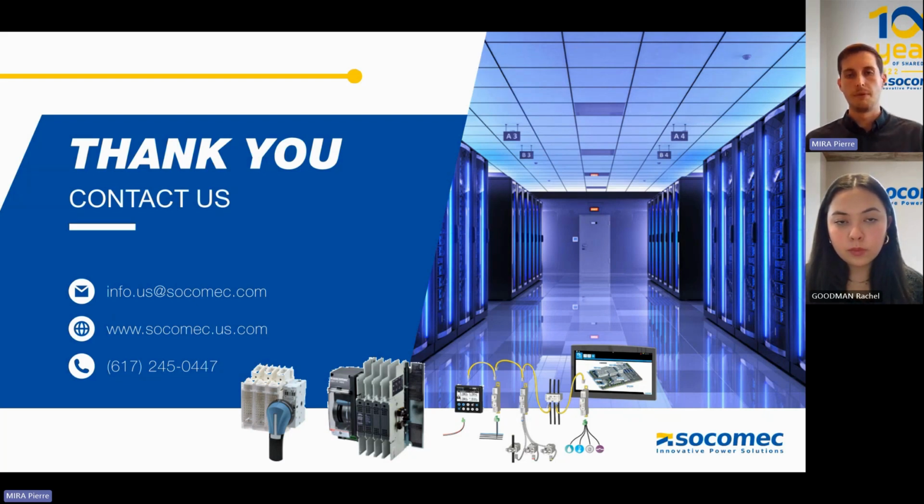We can ship a power module to a service center and service it. Or when we remove the power module, we can open this power module. Through the diagnosis, we would be able to identify which component had failed, if it's a PCBA, a fan, a power supply, or an SCR. And fully out of the data center power system, we would be able to service the power module.